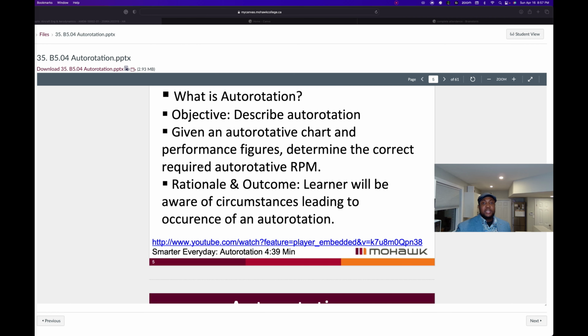The airspeed is a major factor affecting autorotation. It's the pilot's primary control of the helicopter's rate of descent. If you are at 1,000 feet and do not have any forward airspeed whatsoever, this could be troublesome, because it means that you need to sacrifice some altitude in order to gain some forward airspeed.